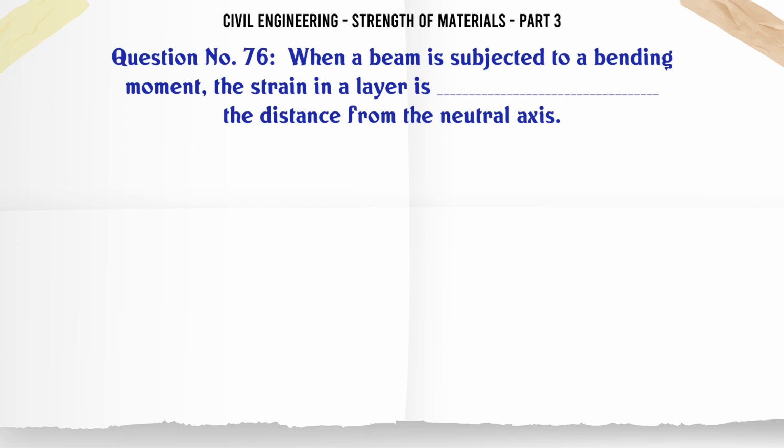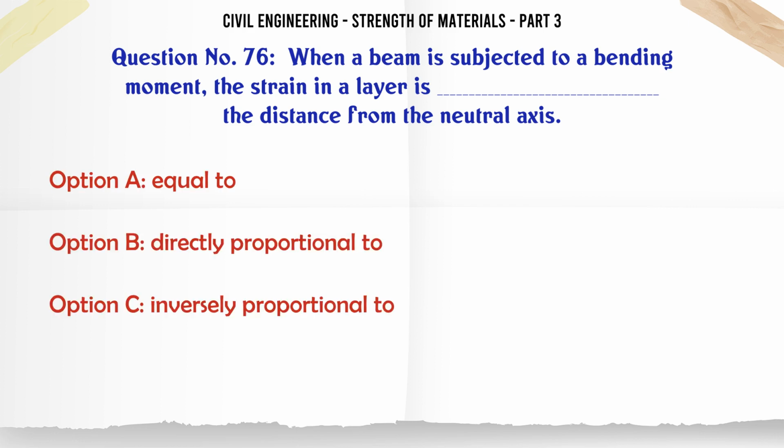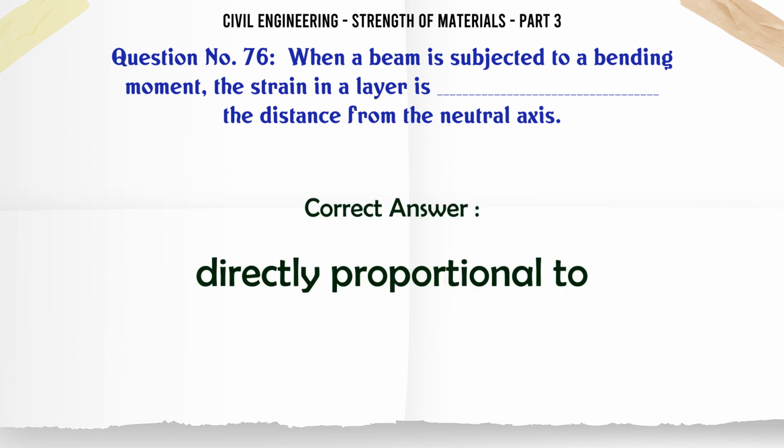When a beam is subjected to a bending moment, the strain in a layer is the distance from the neutral axis. A. equal to, B. directly proportional to, C. inversely proportional to, D. independent of. The correct answer is directly proportional to.